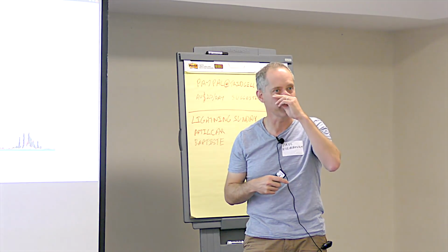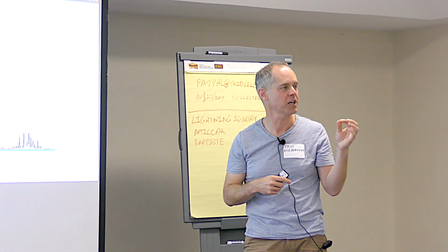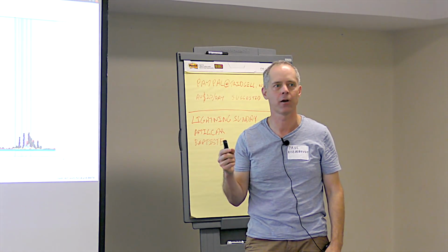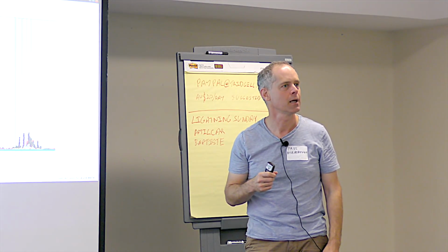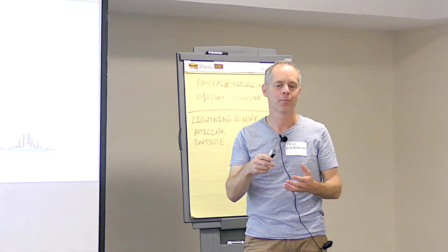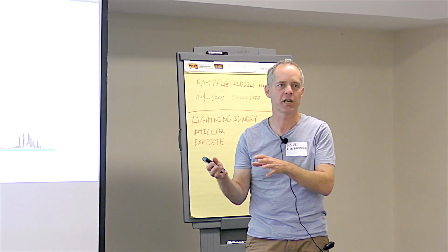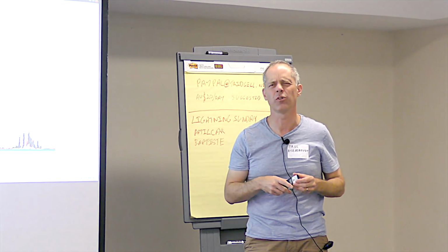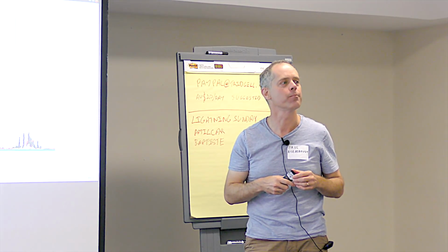This is a severe error. This is something that we have protection for in the Copter code. If you take off and you enter this condition, we have what's called an EKF failsafe, and that will be triggered by large innovations, rejection of the GPS, and then it will go into, I think the default is land mode.